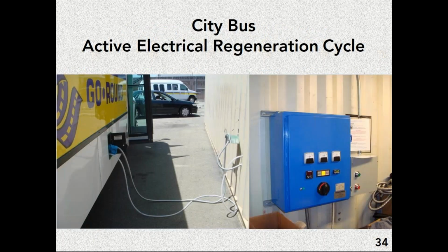You can see here where a transit bus is parked right next to a plug where the unit is actually plugged in, and it's getting power in the right voltage and wattage and amperage in order to make that system burn off the soot. So the kind of duty cycle that one of those buses has is exactly what I was saying is a problem for burning of soot. This would be one that's stop and go, local city traffic, doesn't pick up a lot of speed, it's just going from one block to the next. So those types of systems are almost always producing more soot than they reduce.